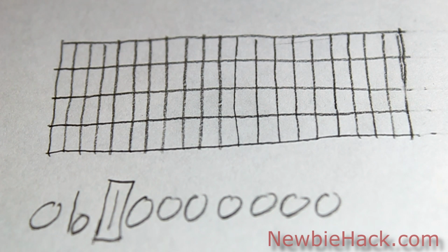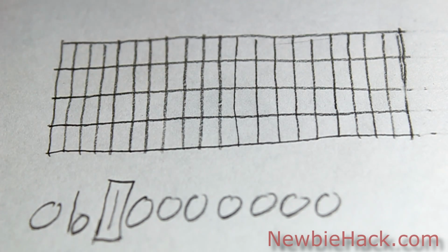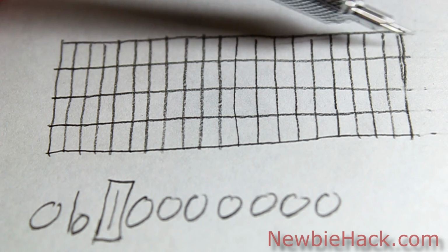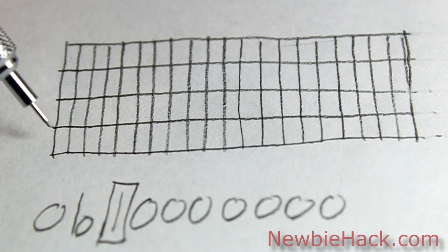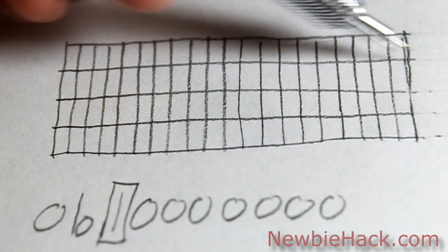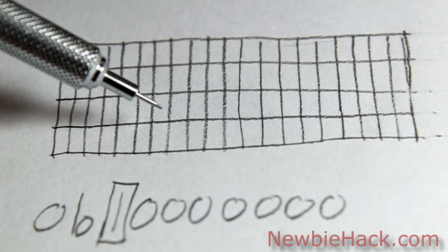Because there are so many varieties of LCD, these numbers are not going to be as easy as, say, 0 through 20, then this will be 21 through 40, 41 through whatever. It won't be as easy as that, because there are displays with more rectangles across on one line or fewer rectangles. So we will need to find out what the numbers are for our particular LCD. You can do that by actually running a program and displaying a number, let's say on the bottom right hand side, and running sort of an X throughout the entire set, and the number will tell you what number that is. That will be actually our first project.